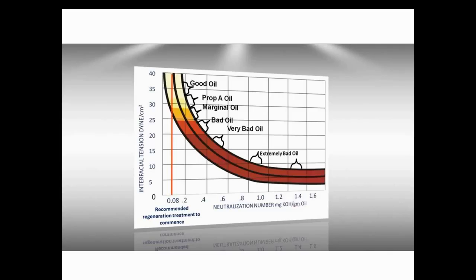But in those days, transformers were very big with lots of oil and paper, thus they could go ahead until that value. But today, if the customer has, let's say, a 500 MVA transformer, it's going to be small for the same amount of power. So both the oil and the paper have to work much harder, because transformer manufacturers try to keep the cost down, saving oil, steel and paper within the same effectiveness of performance.